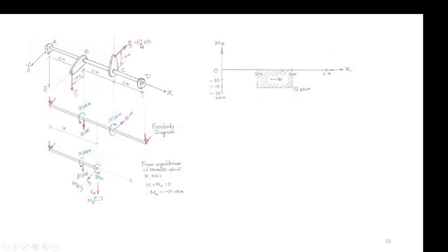So P2 is 10, and since this system is in equilibrium and the supports need to release the moment about the x-axis, then this is the bearing support, so they cannot withhold the moment, so they have to release the moment here. So the only way the system can be in equilibrium is if the total moment P2 into 1.5 distance is P1 into 1.5 distance. Since the distances of the bell crank mechanism are the same, P2 is equal to P1 is equal to 10 kilonewton. So if this is so, then this is the free body diagram of the entire structure.